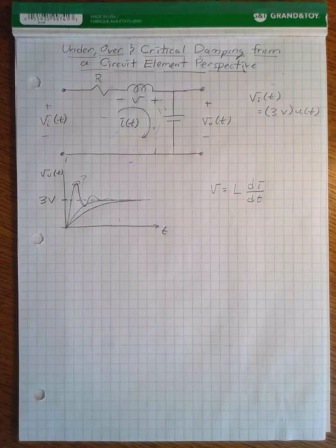And so, from a circuit design perspective, you could ask yourself, okay, big picture, what do I want? Do I want an underdamped circuit? Do I want an overdamped, critically damped circuit? And the answer, of course, as always, is it really depends on your application. As we're going to see later on in this module, when we talk about oscillator design, we want underdamped. An oscillator is a special circuit that creates a varying voltage signal, often used to clock digital circuitry, for example, or used in radio circuits. And so in that case, we want to design our circuit to be as underdamped as possible.